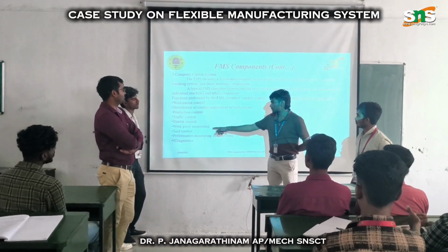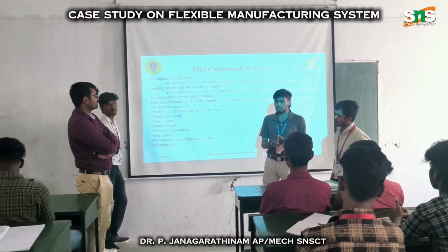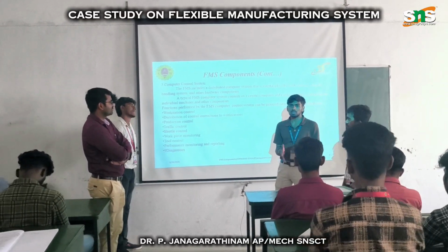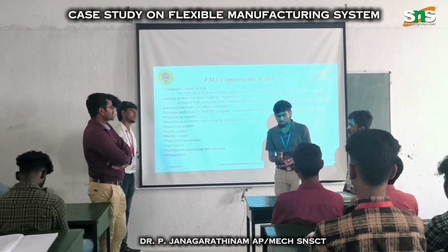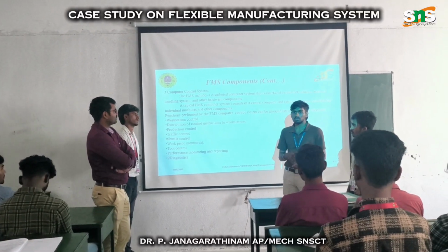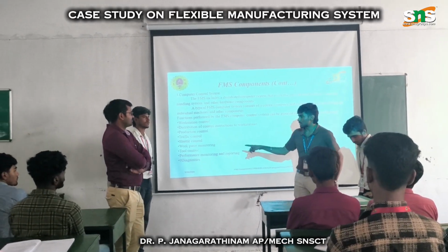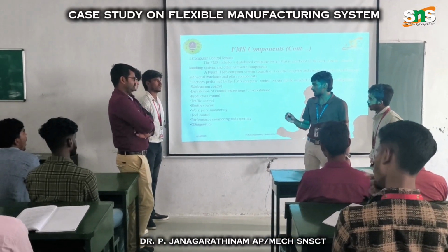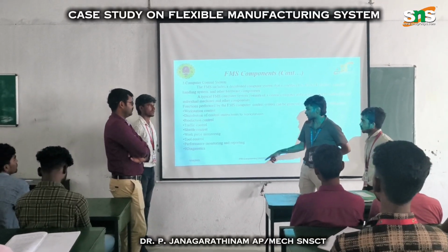Then workpiece monitoring, tool control. Here the workpiece monitoring and tool control is a safety feature that ensures the workpiece and the tool are not in high force contact, which would cause damage because of the high force or momentum. So we use the control system to maintain the precise amount of gap and space for the workpiece and tool. That is why we are using workpiece monitoring and tool control.